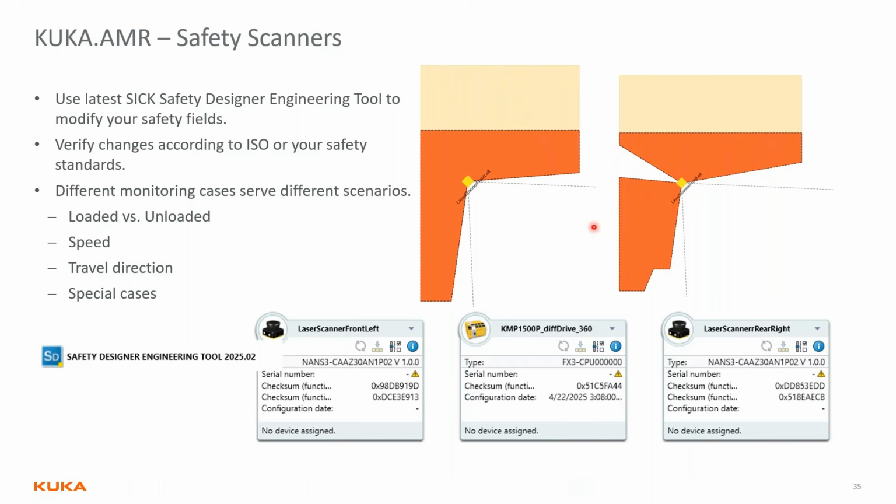Awesome, thank you. Another one here: is there a way to disable path replanning to make the AMR wait for obstacles to clear? Yes, so you can disable obstacle avoidance. If you don't want the AMR to go around the obstacle, you can disable that, then it would wait.